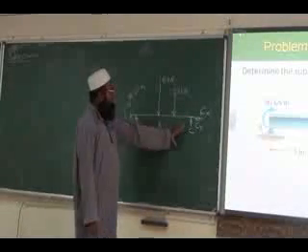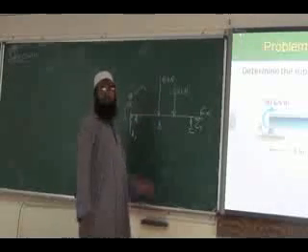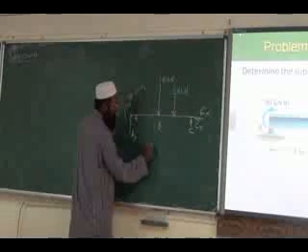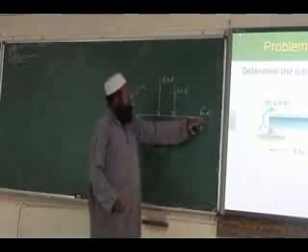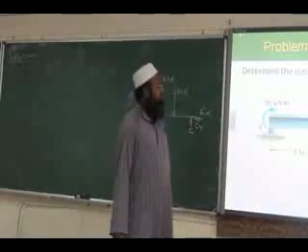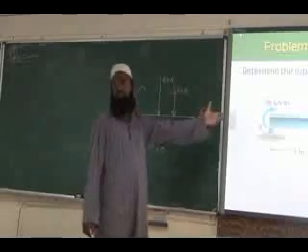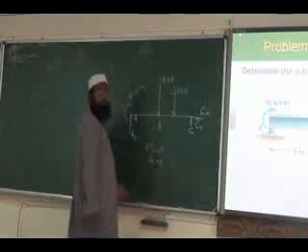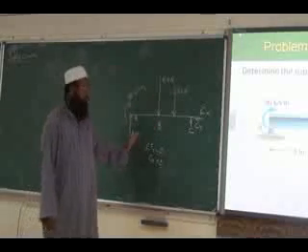Now, after drawing the free body diagram and showing all the forces, in order to find CX, we first use the sigma Fx equation. Sigma Fx equals 0. There is only one Cx. So sigma Fx, can we have any Fx here? There is no horizontal force at the moment. So sigma Fx is 0. So you will say your Cx is 0. As per the given applied system, your Cx is 0.